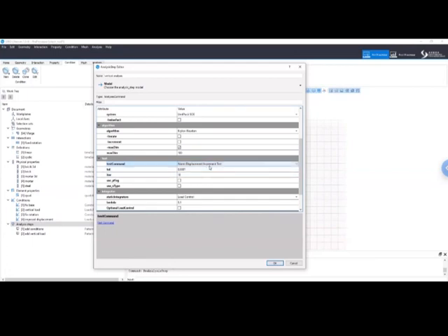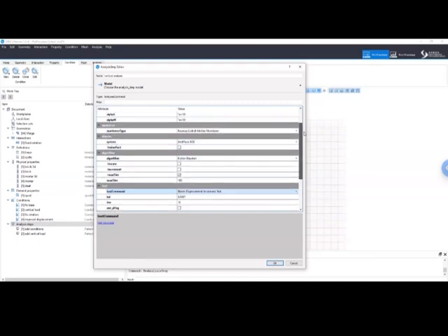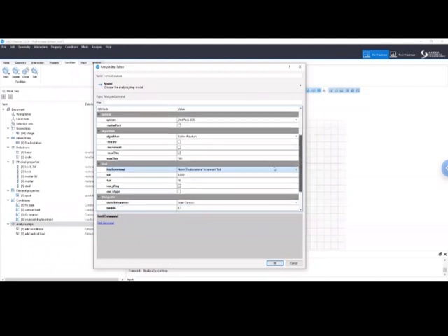Why can you not use the residual vector? Because the penalty constraints are actually adding the reaction forces as forces on the residual vector, so they will never go to zero. That's why. So let's choose a norm displacement increment test. Let's choose 1e-5 as a tolerance. And let's put here, let's say, 100 iterations, even if we will never reach so many iterations.